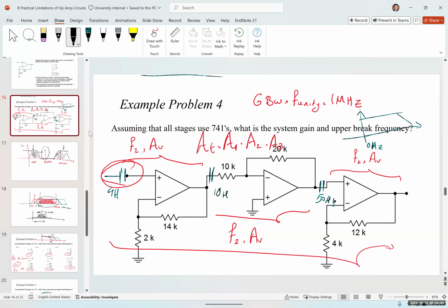As long as your heart rate is around 1 hertz, normal heart rate, it doesn't have a problem capturing the data and getting the signal. But when someone is running, for example, the heart rate elevates, goes up to like 140, 150, sometimes close to 180. And that is the frequency which is closer to these power lines and so on.